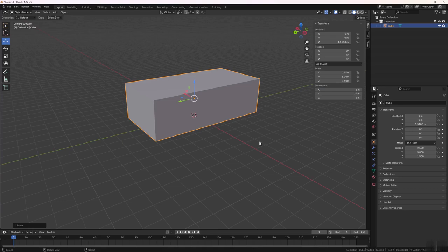So let's fix that. So if you hold down Control and press A, you'll get this apply box up. And come on down to rotation and scale and click on that. Before I do, I want to explain. So the rotation actually, when we look at it, is 0, 0, 0. So the rotation is correct. But I always, just as a standard thing to do, always click on rotation and scale. In case there is an issue with the scale in the future of different items we work with, it's instantly corrected too. So rotation and scale, there we go.